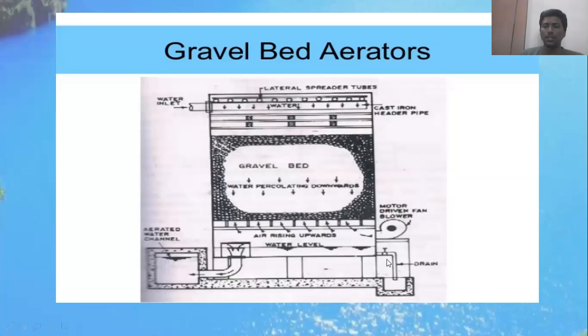Okay, so there is another portion wherever any of the turbid content is provided, or if it has a huge amount of suspended particulate matter. Then what happens is the settlement of particles occurs, and those settled particles, they have a separate drainage portion wherein that amount of the water which is being retained containing the suspended matter will be driven out. It is being driven away from the treatment plant. Okay, this is what we call a gravel bed type of aerators.